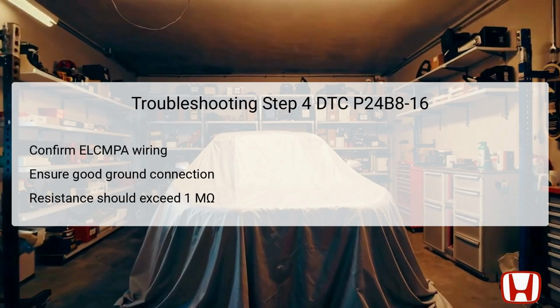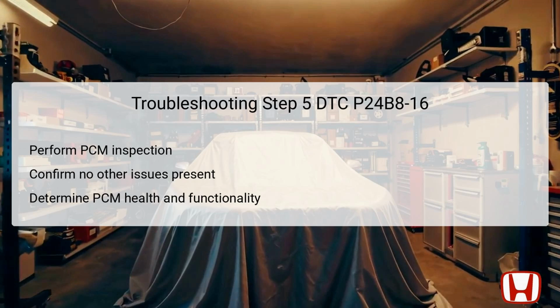The final troubleshooting step is the inspection of the powertrain control module, PCM. If all previous tests yielded normal readings, the concern likely rests within the PCM itself. This module is pivotal, processing information from multiple sensors and controlling various aspects of vehicle performance and emissions.